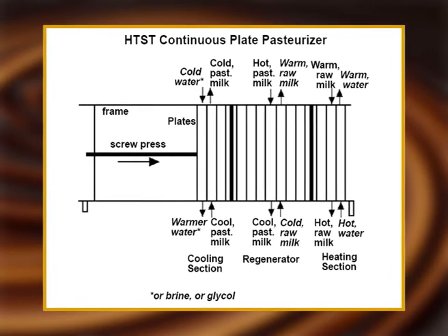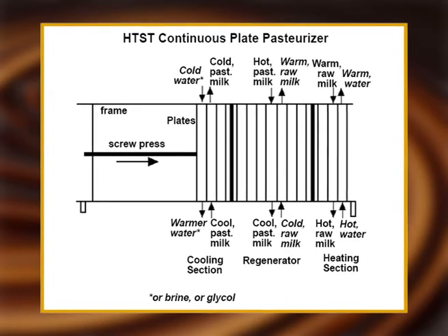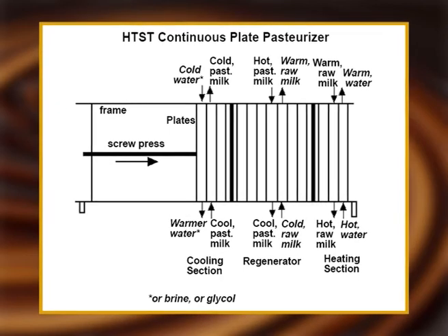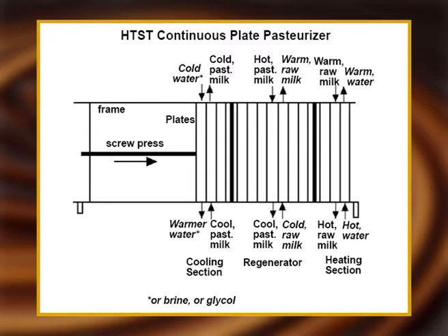Batch tanks are usually operated in tandem so that one is holding while the other is being prepared. Automatic timers and valves ensure the proper holding time has been met.